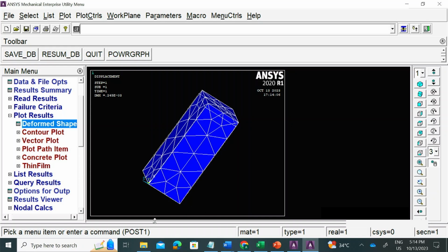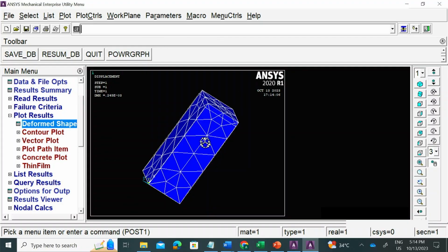The next thing which we want to look at is known as the deformed results. This is just the deformed shape. And one thing to note is, please do not go by the visual appearance. It could be that you have selected a model which is built of steel. Can steel deform this much, by 20 millimeters? It cannot. So this is a visual appearance. You are not looking at a true scale, right?